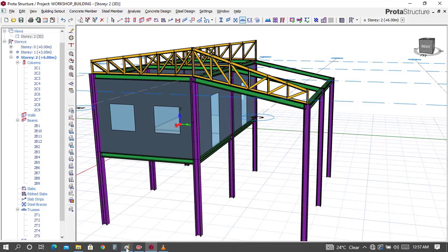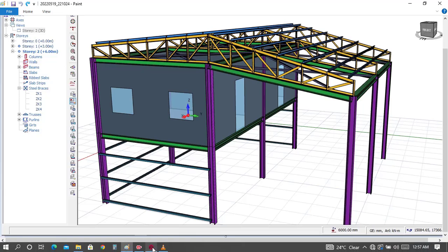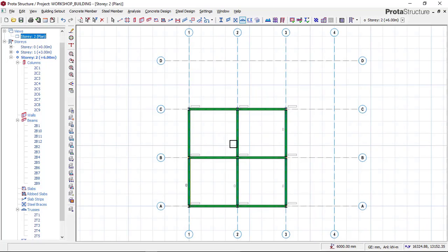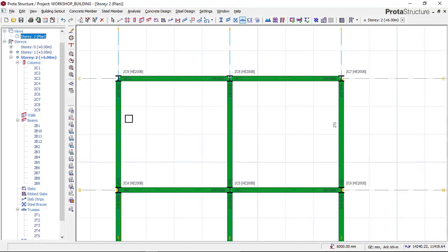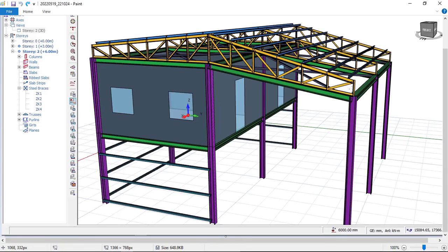Okay, so this is what we have also in this place. Now the same truss repeats itself on these two members. So we will have to repeat the same truss on these two members, here and here. Now we click back on truss. You start your point from here. You don't start from here because we want this short end to be on this face and our longer end to flush with this truss.